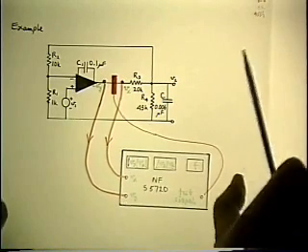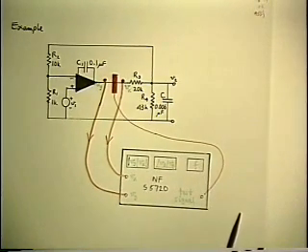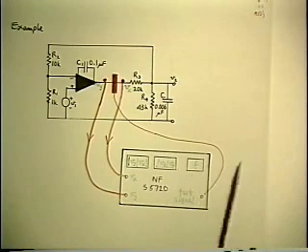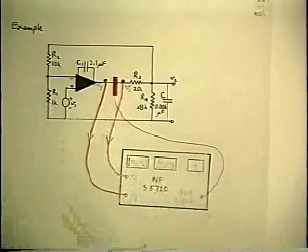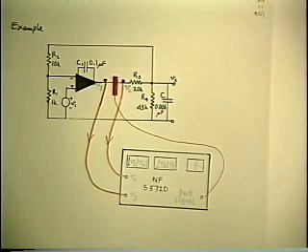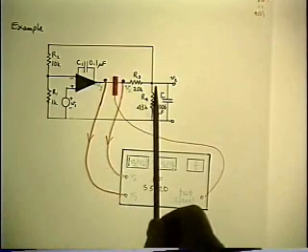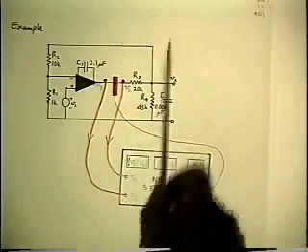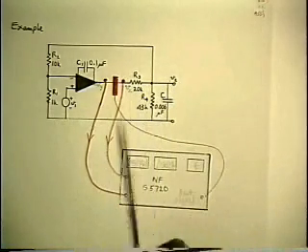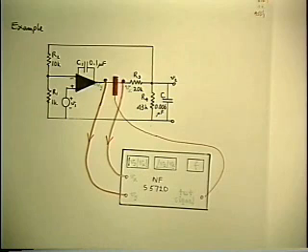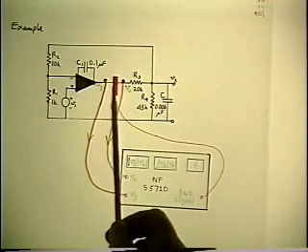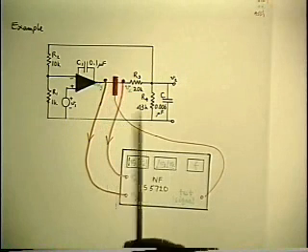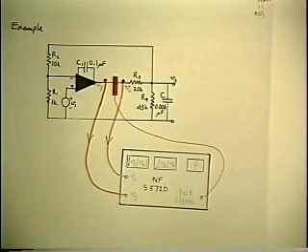And you're ready to go. With your control computer or your hand or whatever, you just go right along and do your frequency run. And you've not broken the loop. You don't have to fuss with applying a bias and adjusting it. And because of using a transformer to do the signal injection as well, you have nothing but 3 probes to hang on. That's all it takes.